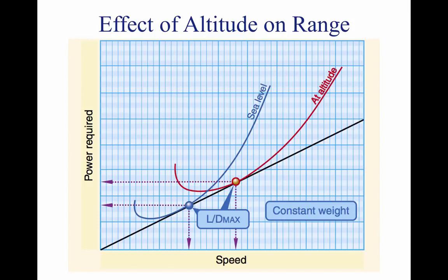If a change in altitude causes identical changes in speed and power required, the proportion of speed to power required would be unchanged. The fact implies that the specific range of a propeller-driven aircraft would be unaffected by altitude. Actually, this is true to the extent that specific fuel consumption and propeller efficiency are the principal factors that could cause a variation of specific range with altitude.